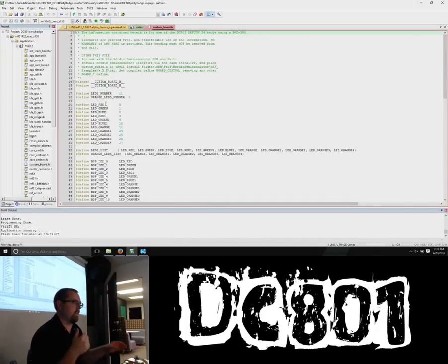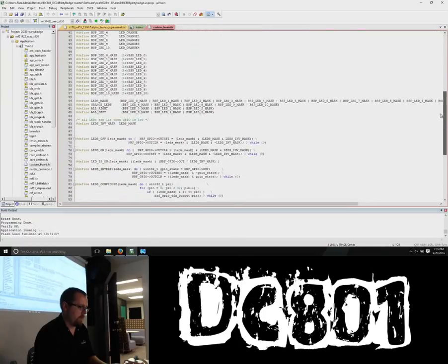So it's basically telling you what signals go where for your program. So when you call out, I want this LED or this device to turn on, this is the file that determines what pin gets that signal. So it's your guide to your program.